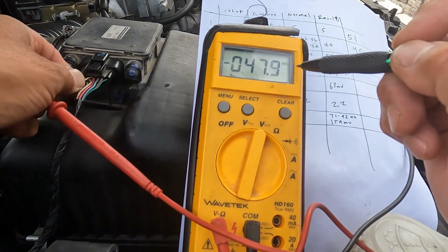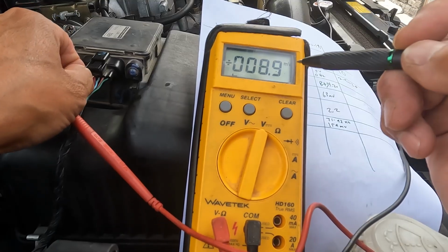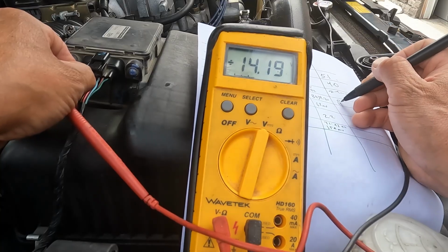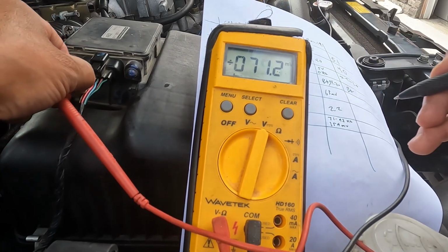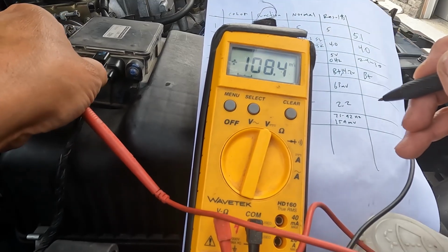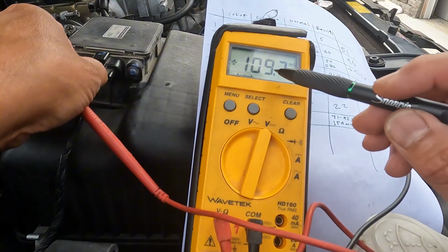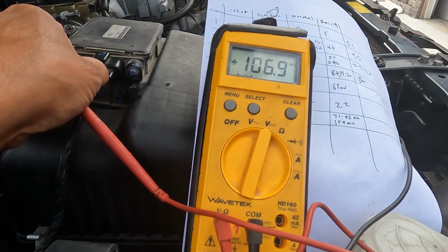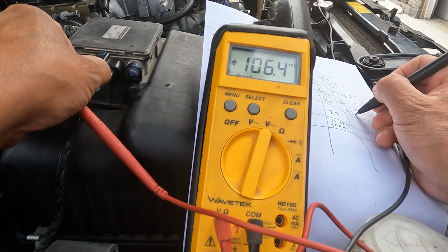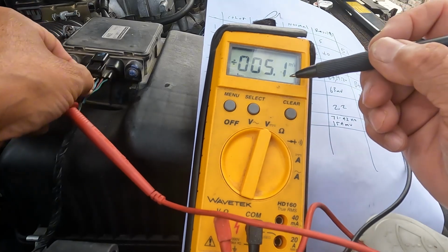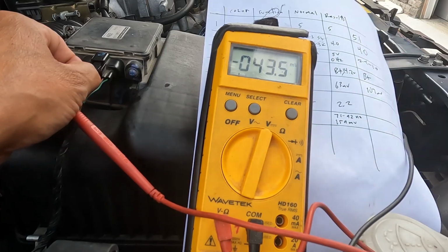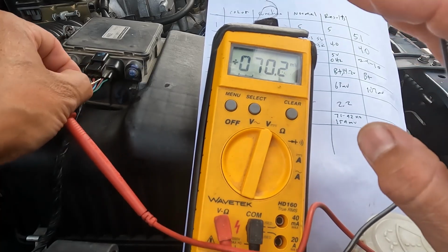Now on the red wire, terminal number 4, coming from the MFI relay, we have battery voltage, just B+ right there. The sky blue wire, which is ground, on this one we have 107 millivolts. That's more voltage than I care to see in there. I'm expecting no more than 0.05 there, or 50 millivolts, but I'm not sure why we have so much voltage there. But we're just gonna keep that in mind.